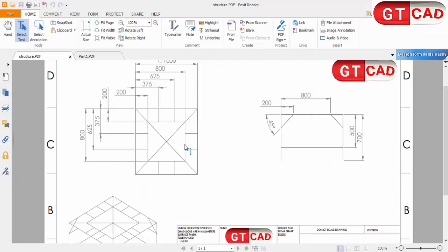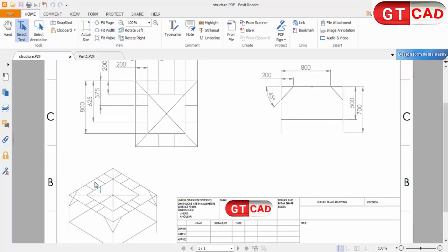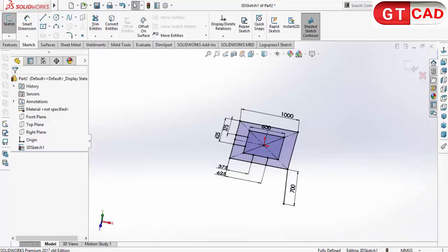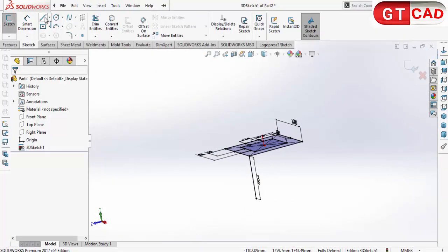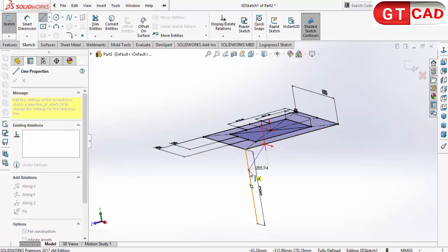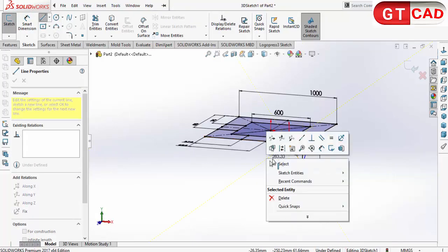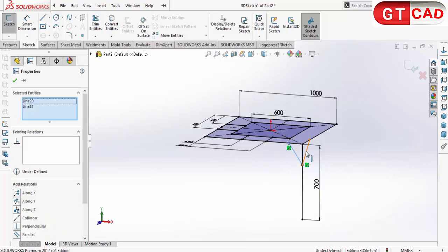This square is done. I created two profiles, the short profile done, and we have the angular line. Let's create it. It's a 45. It means the two lengths of the edge are the same, 200 millimeters. Okay, rotate, make this line and this line equal.